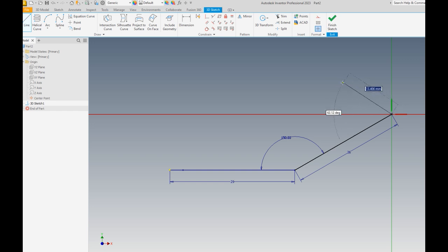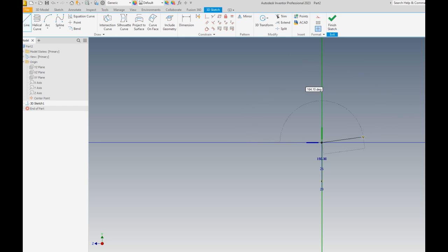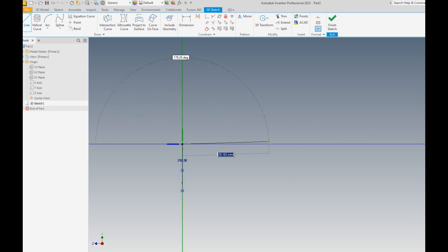So now I have my angle. Once again, I apologize for this. I'm going to use my view cube. The view cube is off screen at this point, but everybody knows what the view cube looks like. I'm still active in line. I'm going to go to the view cube and click the arrow that indicates the right, and that will bring me to the right. Again, holding the roller wheel down, I'm going to give myself a little bit more room. I'm going to pull my line in that direction, and in this case, I'm going to type in 30 millimeters, hit enter. All right.